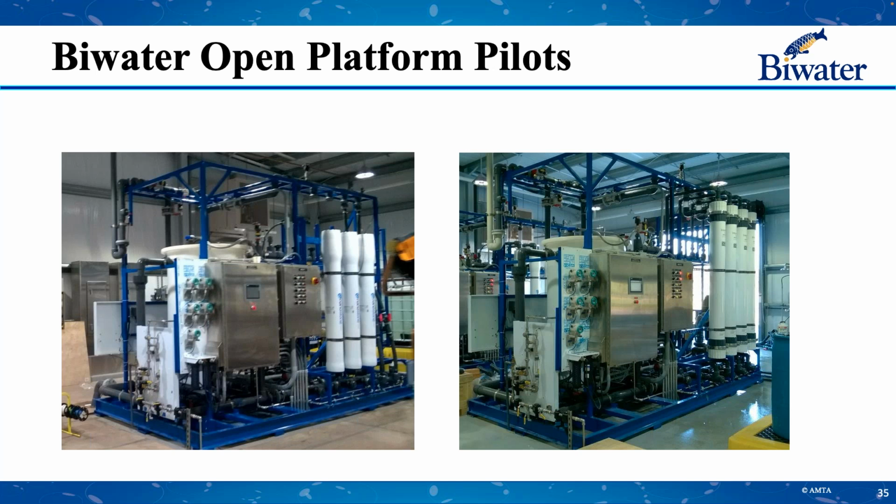Whereas on our parallel mode pilot plant on the right, that's designed for where we're running into slightly the demonstration scale size, where we might want to link up with an RO skid downstream. And generally we prefer to pilot test as close to full scale as possible. So if we're running an 8-inch 2-1 array RO downstream, we're going to need a significant filtrate flow to accommodate testing of that system downstream.